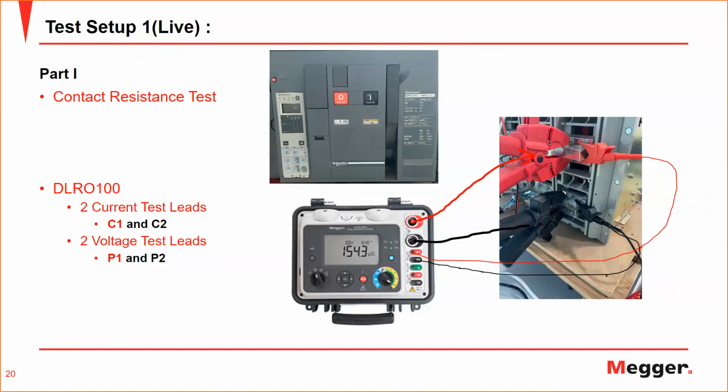Another question is, someone is asking, can this device be used to measure any kind of contact of breakers, joints, or bus bars? Yes, you can measure breaker contacts, joints, bus bars, etc., all of them. And there is one test mode that I did not mention or explain. It's called continuous injection. This is very important when you have, for example, a long bus bar. You can inject across all this bus bar, and then for the joint itself, you measure each joint separately using just the B1 and B2 leads very easily.